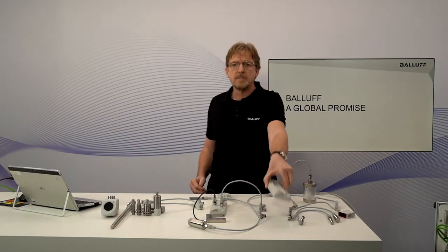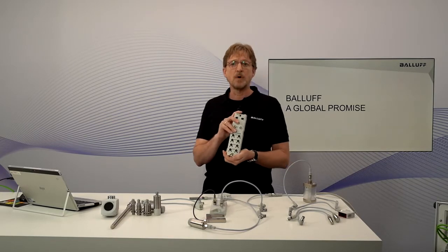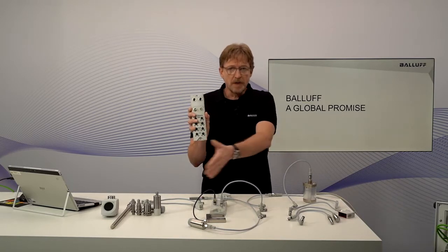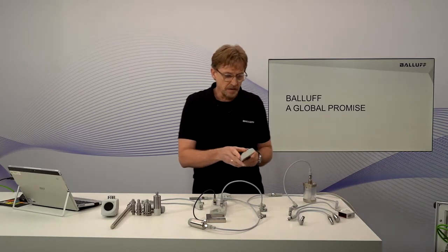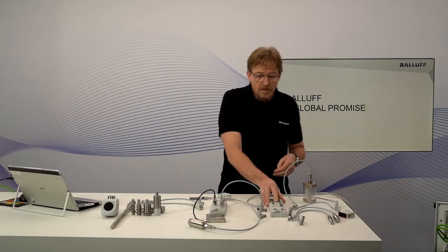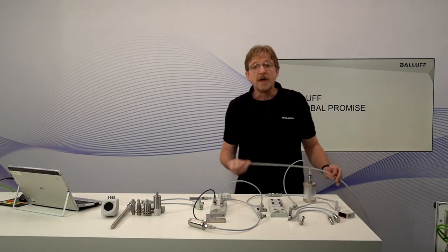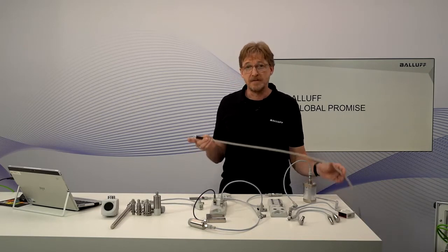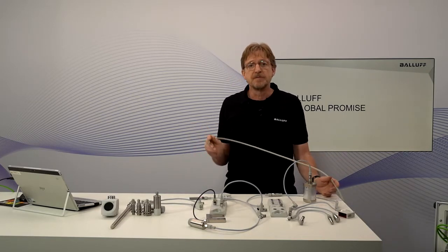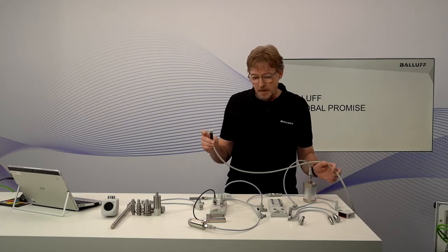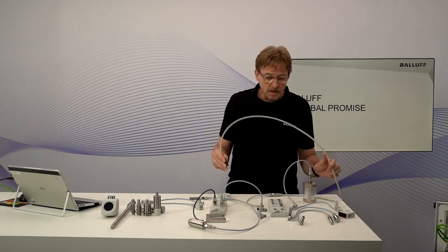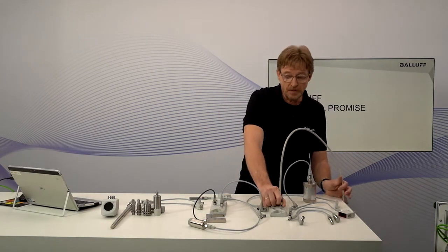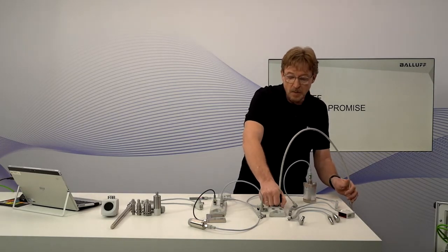First, let's begin with, as I said, the backbone of the system, which is the master module here. To this master module, we are going to connect all these different components here on the table. First of all, we have to connect the power supply. This is the first thing of uniformity: every connection is an M12 connector. Different coding, of course, but we are supplying the power with an M12 L-coded connector, which is this one, and this is what we want to do first.